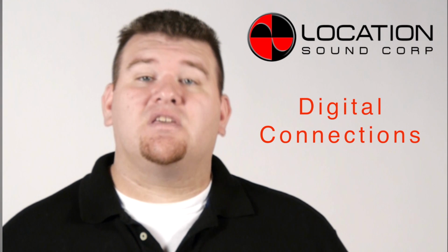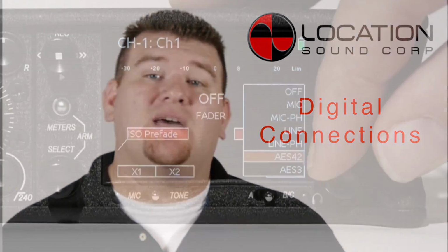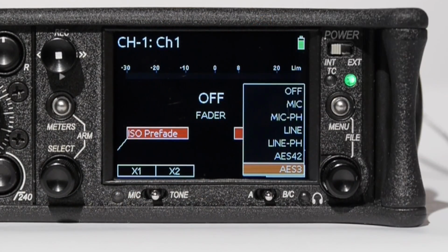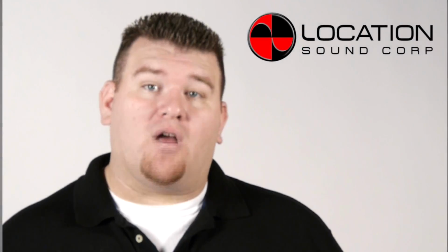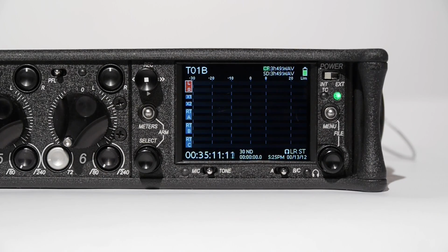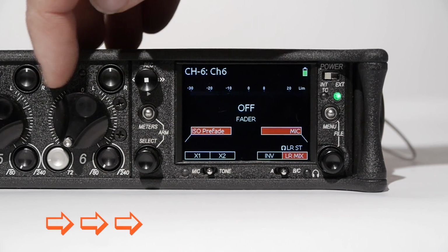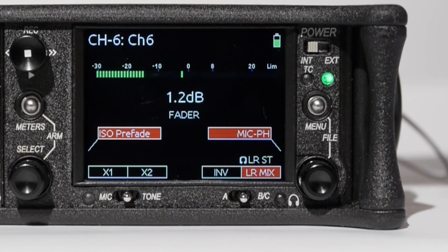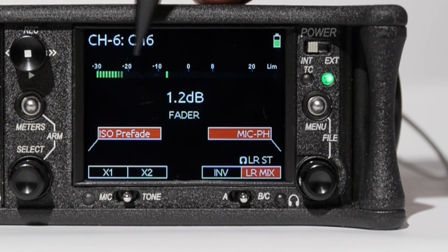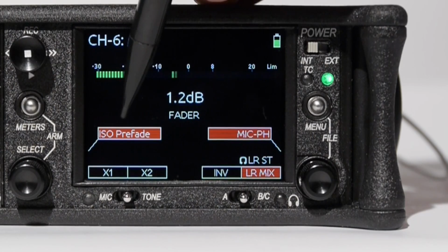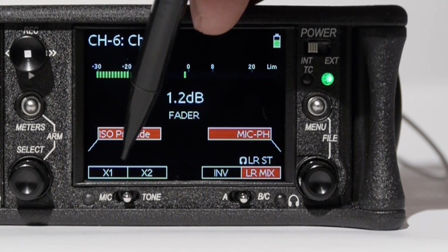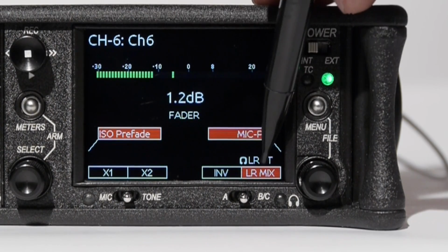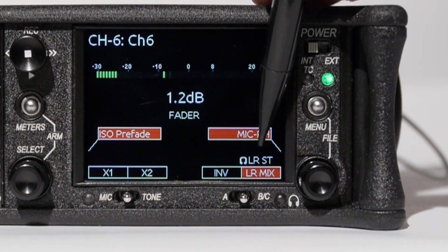For digital connections, inputs 1 and 6 can be selected to accept AES42 or AES3 digital signals for any digital audio requirements. To access the input settings screen, slide the input selector toggle switch to the right of each input. The LCD will display information pertaining to the selected input and provide access to mic, line, or digital input selection, input track name and number, input meters, current fader gain, ISO track status, aux bus assignment, input polarity, left-right bus assignment, and headphone source level.